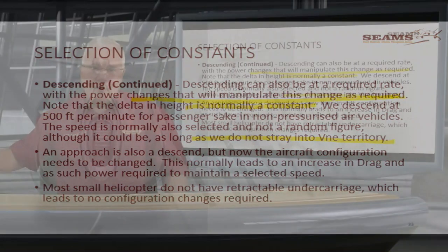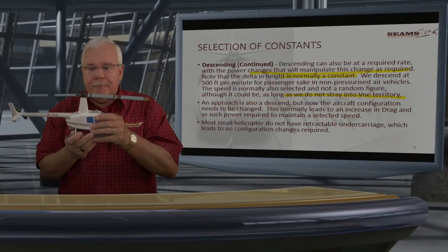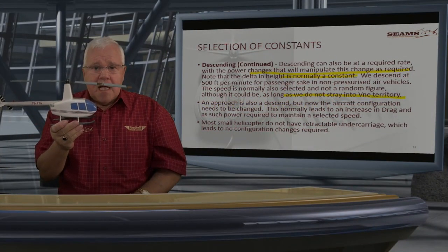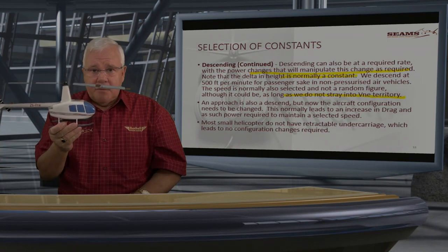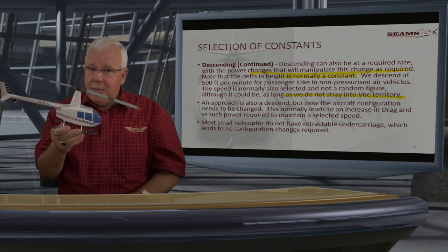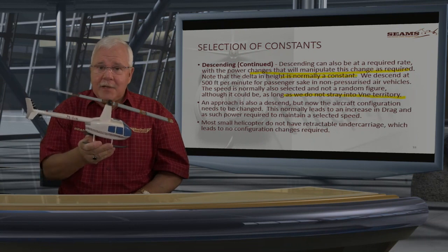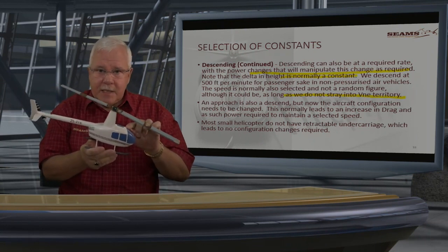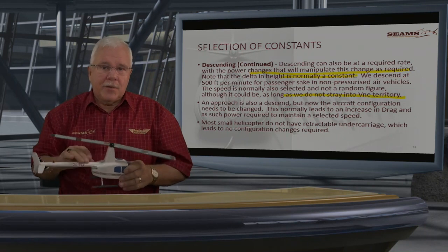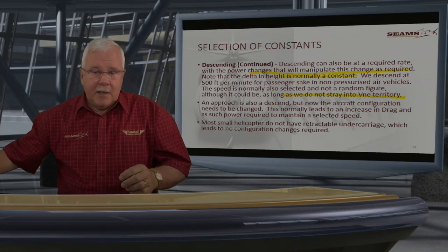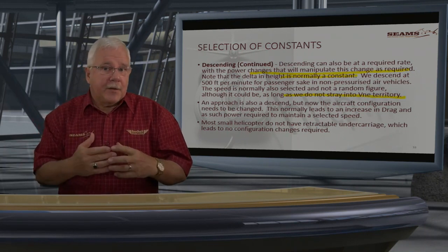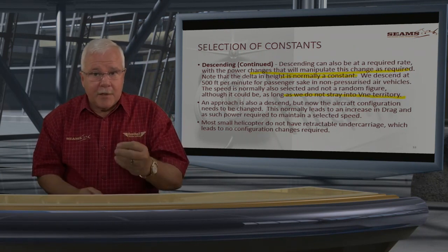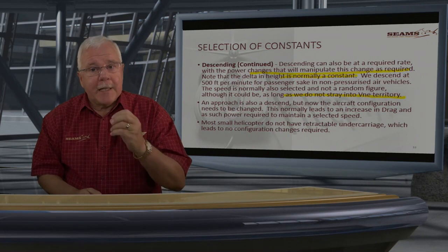But, you know, I was doing 80 knots in level flight, and I've got 2,000 feet to lose. I can simply put the nose a little bit forward and start using the height as extra energy. I'll leave the power where it is, but as extra energy, I'm going to start using up the height. That means that the speed will now increase to 100 knots. That's fine. If that is what you want to do, then it's predetermined and that's how you want to do it.